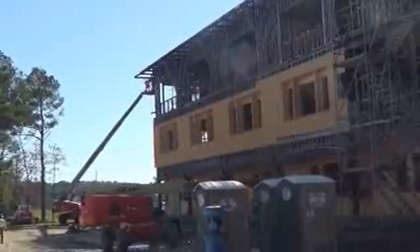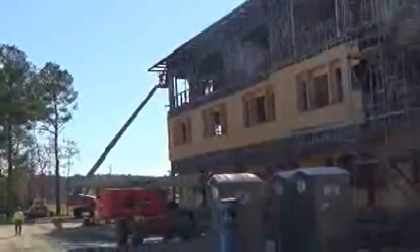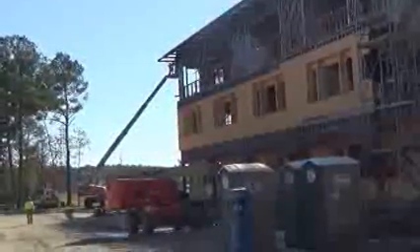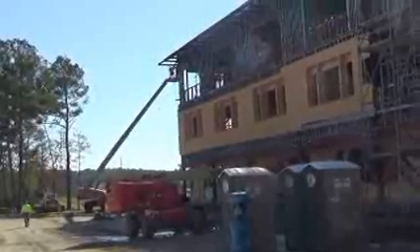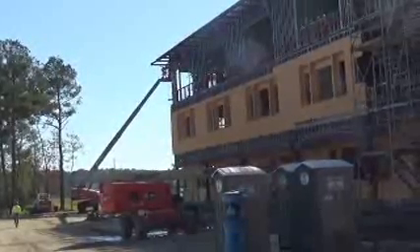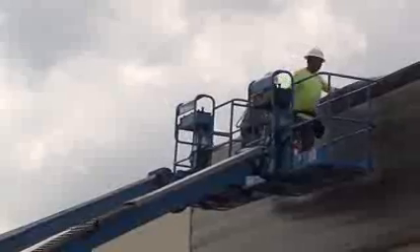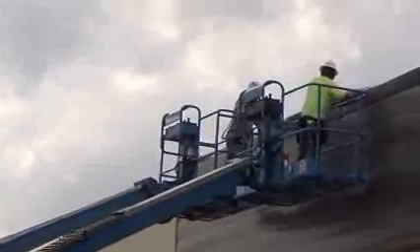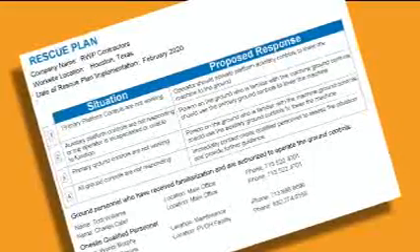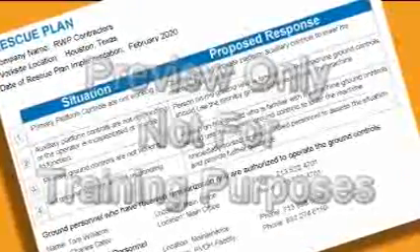The risk assessment must include rescue planning to ensure the safe and timely rescue of workers from heights in the event of an MEWP breakdown, platform entanglement, or a fall from the platform. A written rescue plan must be created and incorporated into the company's training procedures, which addresses falls from the platform.